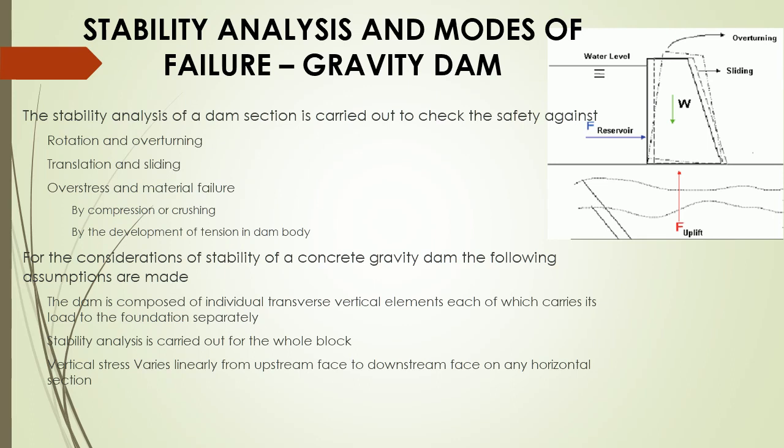The dam is composed of individual transverse vertical elements, each of which carries its load to the foundation separately. Stability analysis is carried out for the whole block. Vertical stress varies linearly from upstream face to downstream face on any horizontal section.